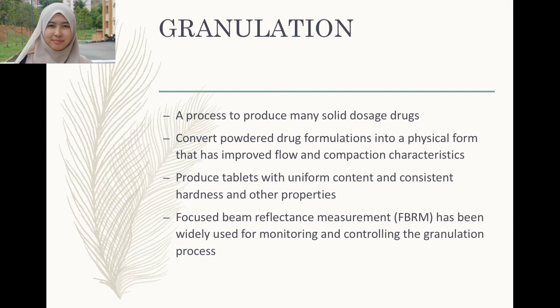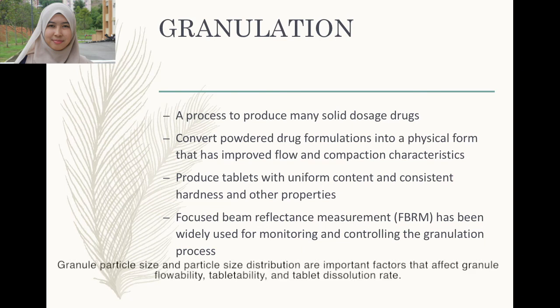Next, what is granulation? Granulation is a common technique for manufacturing solid dosage forms such as tablets and capsules. It is often necessary to convert powdered drug formulations into a physical form that has improved flow and compaction characteristics in order to produce tablets with uniform content and consistent hardness. Granule particle size and particle size distributions are important factors that affect granule flowability, tablet ability, and tablet dissolution rate.